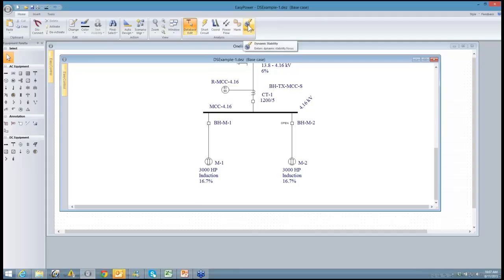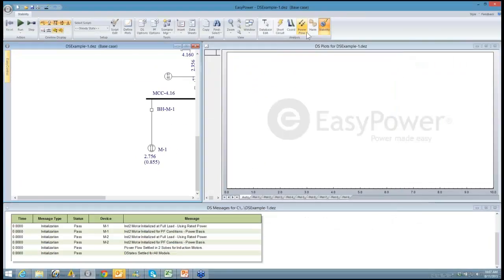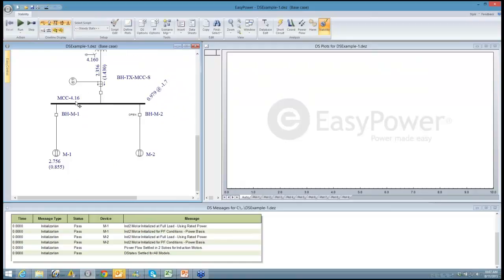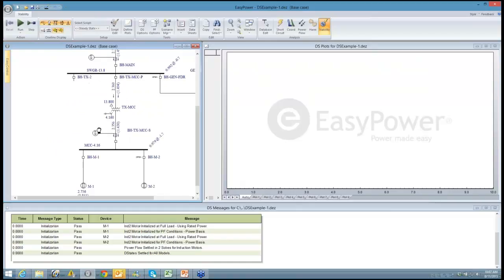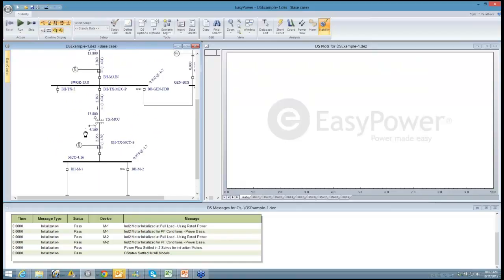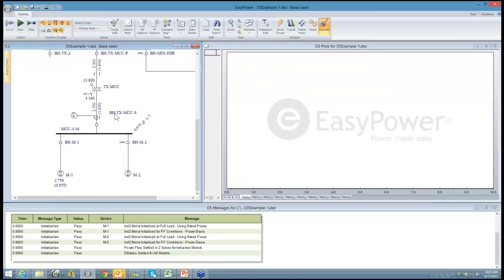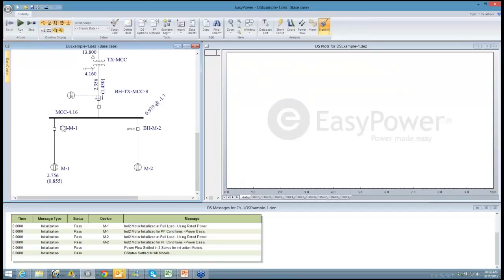All right, so at this point, we have the ability to go in and look at some stability performance. So let's do that. I've gone to the stability module, and in this case, we're working specifically on transient motor start. And so you'll see that the tool launches in a state where we've solved the PowerFlow equations, and in this particular case we have one motor breaker closed.